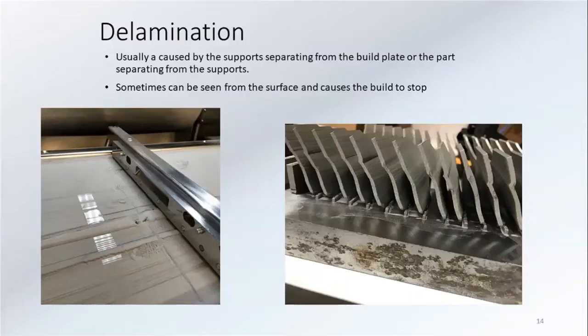So you can typically find, depending on how quickly you transition from supports to parts, if it's a 3 millimeter gap, so you're using something like a wire EDM to cut it back off, 2 hours is about sufficient to watch your build. But you really need to start the build and have someone there to monitor it, especially if you're doing a new type of part, a new support design, any of that, because that really affects it.